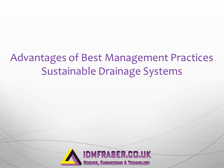The advantages of SuDS. To improve the water quality and reduce pollution in the natural environment, the surface water drainage management and source control techniques have been developed. These are sometimes referred to as best management practices, or sometimes by the acronym BMP. More recently, these have been called Sustainable Urban Drainage Systems, or by the acronym SuDS. As these techniques are now used both in urban and rural locations, the word urban is very often dropped from the name.